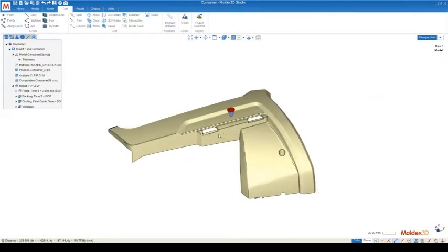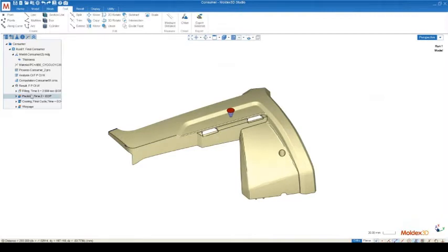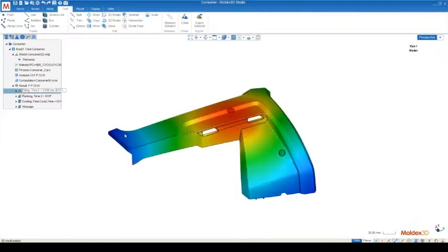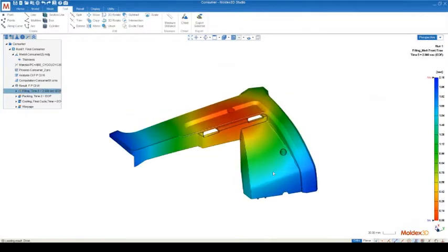So that's how you can optimize your filling time before you run the simulation, but after you run the simulation, there's also more optimizations that you can do. So just looking at my filling results, honestly, the filling time doesn't really tell me anything. The filling time just tells me how much filling time I actually input into the simulation. In this case, it was about 2 seconds.